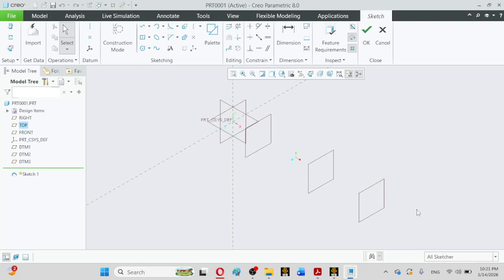One important thing that you must note is that you cannot create a point section when you are demonstrating this command externally using external sketching. If you want to use a point as the section, you must demonstrate this command internally using internal sketching, with the sketch sections feature. At this stage, for example, I am just creating a circle here at this location.